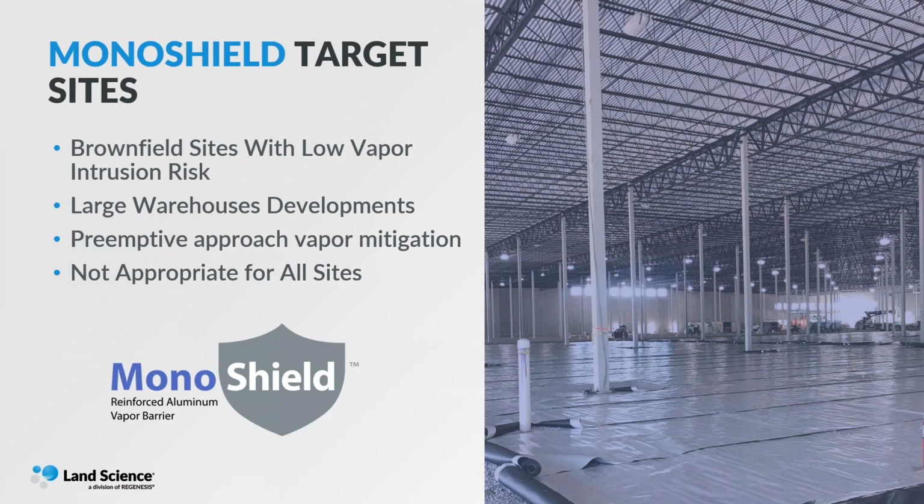So there's been a proven market and need for this preemptive vapor intrusion mitigation at what some might characterize as a low-risk site. This market has been traditionally served by a thin mil plastic sheet that's designed more often for moisture and water vapor barrier protection, not for contaminant vapor barrier. These systems are not chemically resistant and are constructed with tape seams often, and the tape seam penetrations are highly susceptible to contaminant leaks and/or damage from underslab conditions.